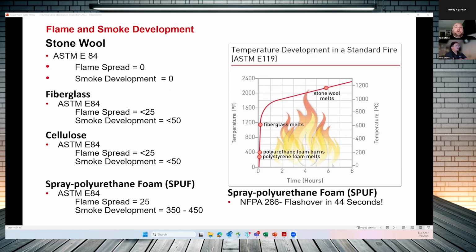Now, I'm a big believer that all these tests are cool and great, but what does it mean in practice? What does it mean for us builders, us designers? What does that actually look like? Well, I was on a project up in Maine where they had the roof line insulated half with fiberglass and half with rock wool. When I walked up the stairs and looked up into the rafter bays, I could tell the exact bay where it went from fiberglass to our product, because it was charcoal plywood and then beautiful blonde plywood again up in that roof assembly.